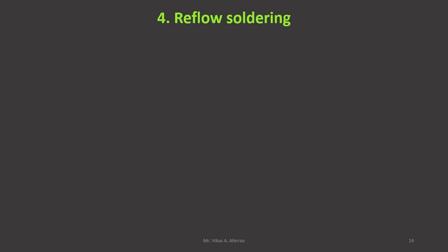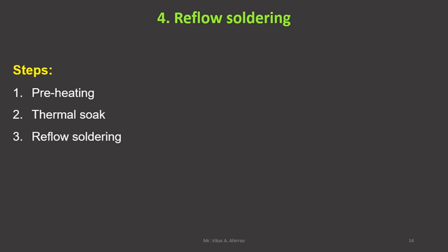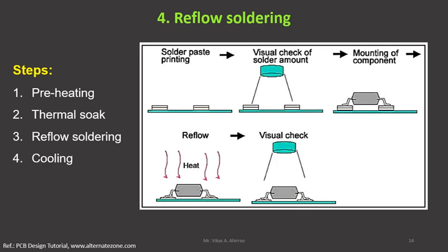Another method is also available, and that is reflow soldering. Reflow soldering is very similar to the wave soldering process with a few exceptions. The steps in reflow soldering are: first the preheating, second thermal soak, third reflow soldering, and fourth the cooling one. If you refer to the figure,